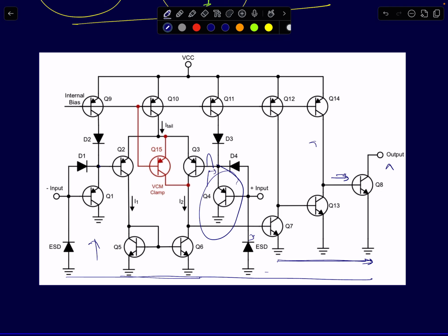That's the reason for adding a common collector input stage. So even though it's giving a gain less than 1, the main reason is that it adds a very low output impedance, so it decreases the inverting node's impedance, and therefore it decreases the kickback jump, which in turn makes the comparator's output stable.